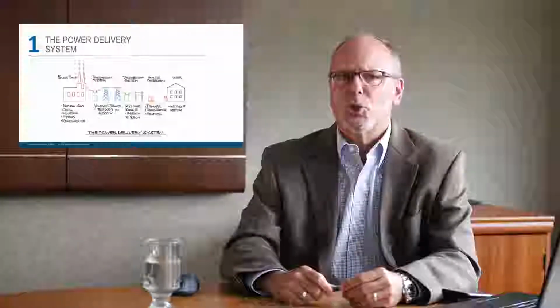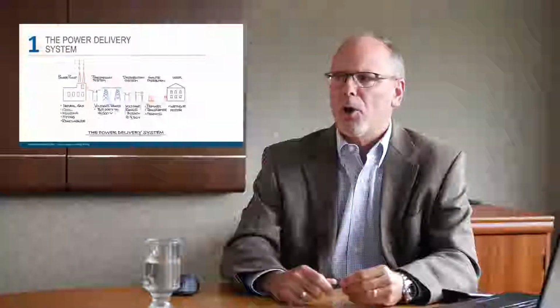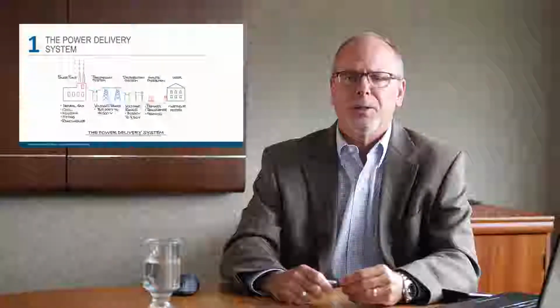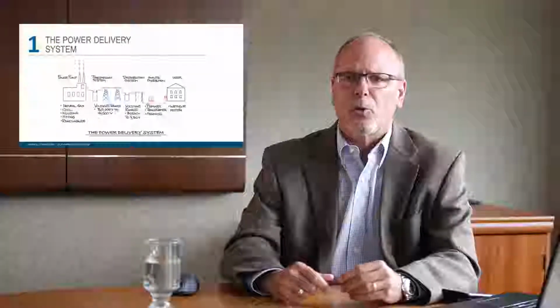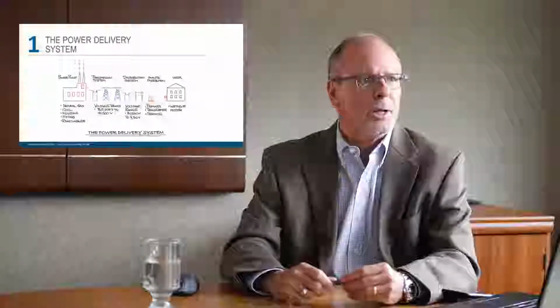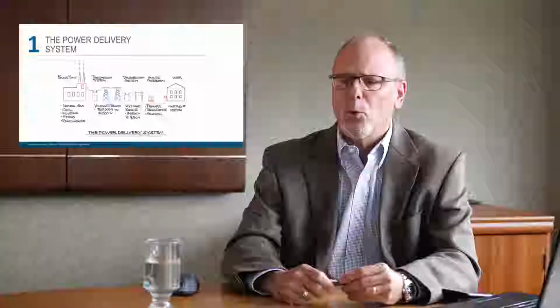Once the electricity is generated, then it's transmitted over a transmission system. These are typically what you see running across the countryside, the steel tower lines or large steel poles. Voltages on these systems range from 44,000 volts up to 750,000 volts, and their purpose is primarily to move the power in bulk from the generating locations to the centers of load like cities, towns, or large users.